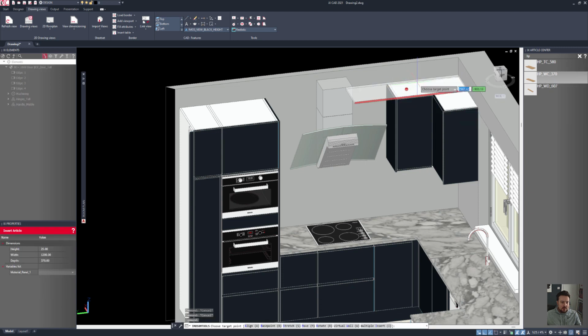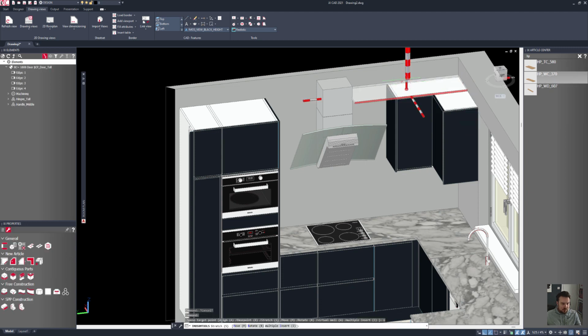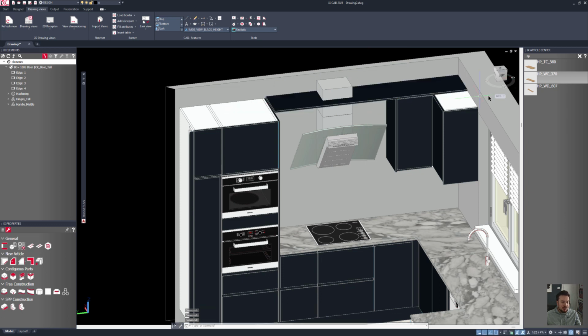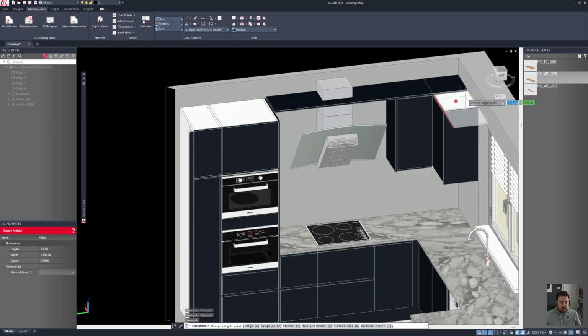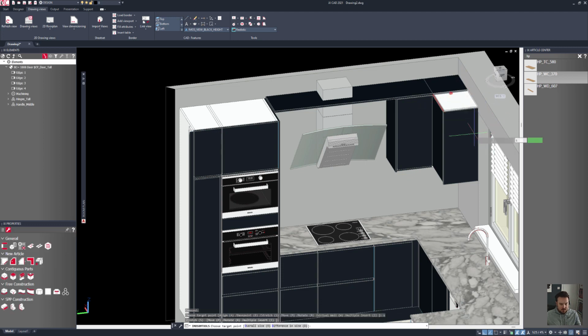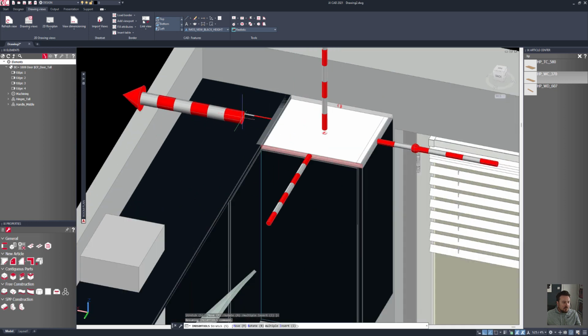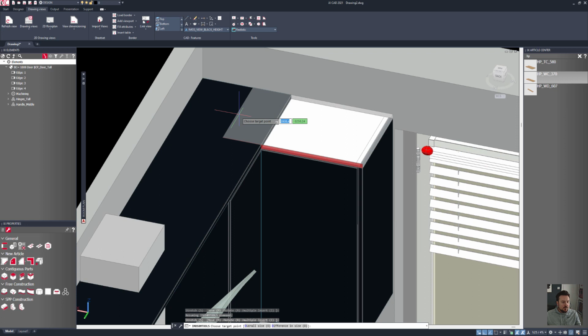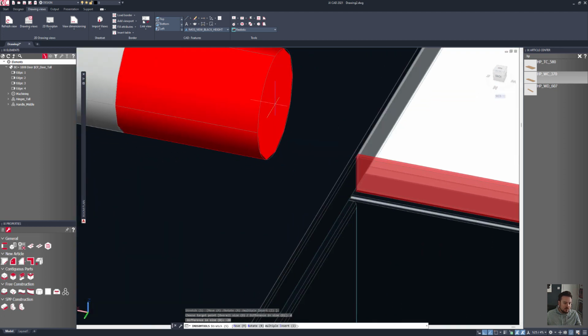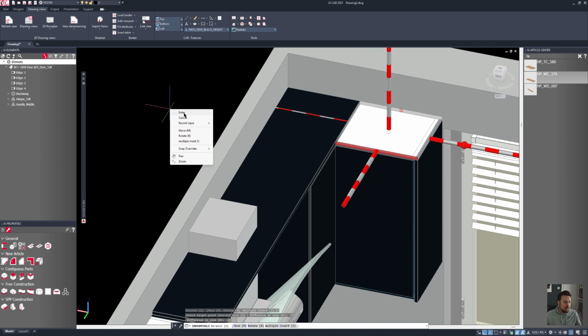so I'll just say that that should go on the top, and I'm just going to stretch this all the way across to form like a bridging unit, and then I want another one in here and just say stretch back. Now in here I might want that to tuck back in a little bit further, so again I'll just stretch and say difference minus, I think it's 20 millimeters in here, maybe a little bit too much, but we can check.